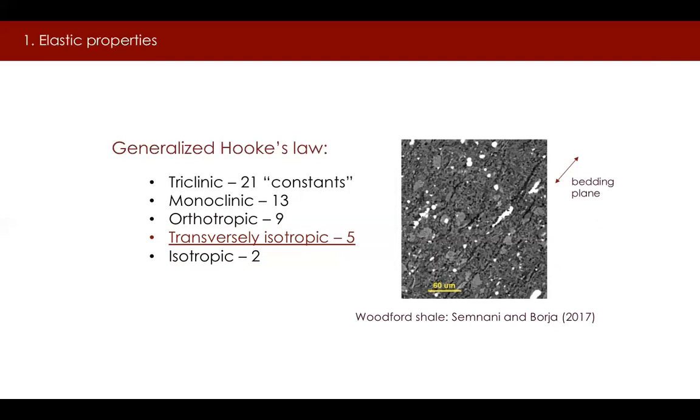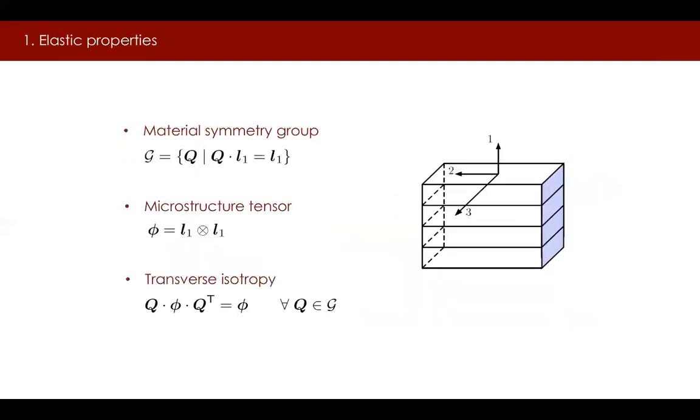A more realistic type of anisotropy for shale is that of transverse isotropy due to the existence of bedding planes that resulted from the genesis of the rock. With respect to this type of anisotropy, the bedding plane represents the plane of isotropy, whereas the axis perpendicular to it is the axis of cross-anisotropy. Usually, the bedding plane is the horizontal plane because of the manner in which the sediments were deposited.